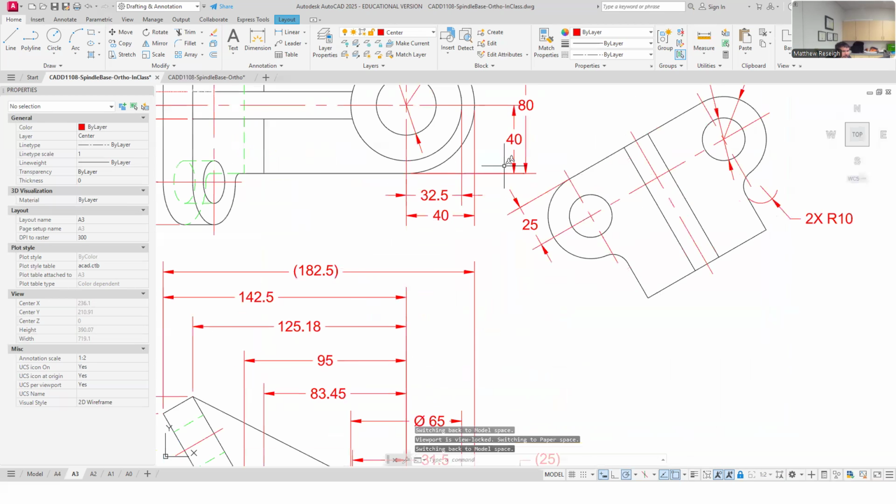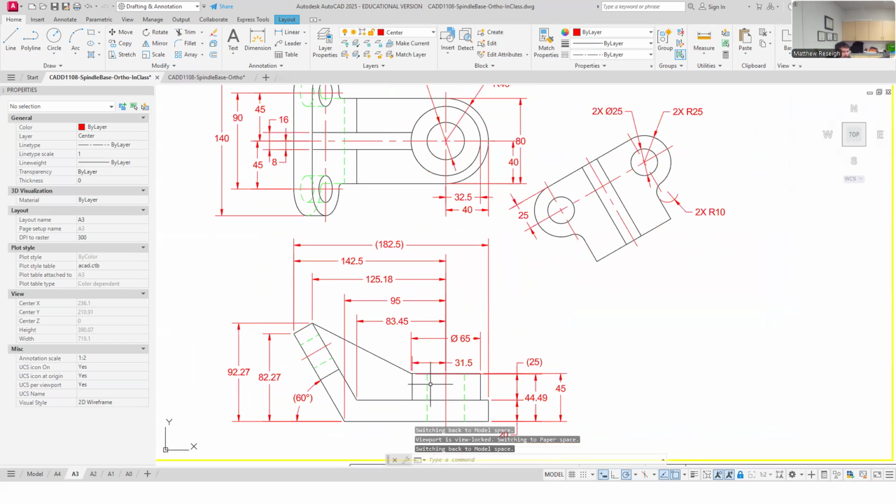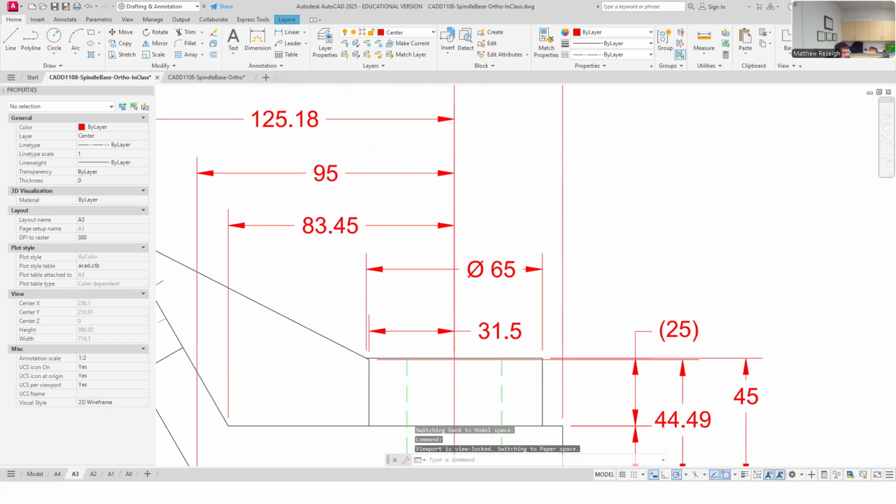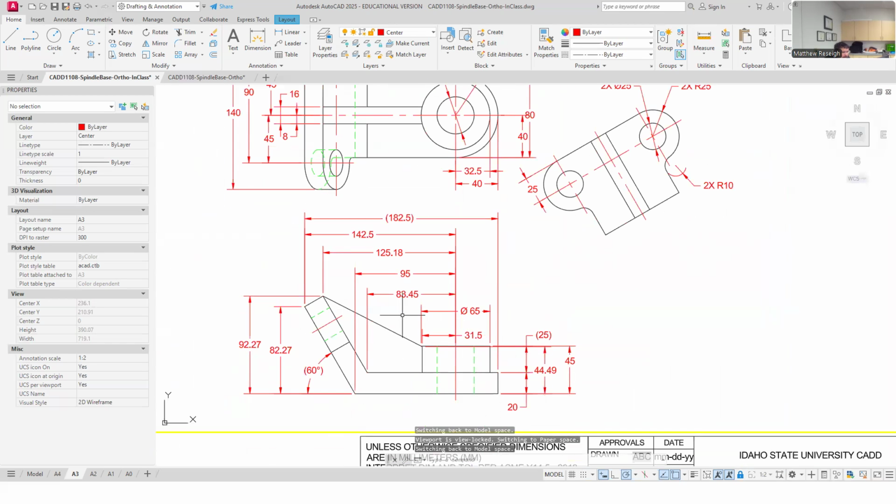And if I didn't have room, I mean, I haven't established my room, but the moral of my story here is just watch that your spacing isn't getting crowded. I did figure out that I was going to be at a half inch or half scale before I started dimensioning, so my scale factor didn't change my dimension spacing. But just watch yourself if you end up not picking a good scale factor first, and then you adjust that scale factor. You may have to go back in and respace stuff. Just watch the stuff doesn't get super overcrowded if you flex your scale.